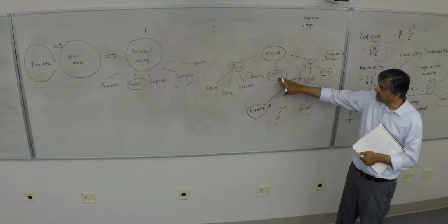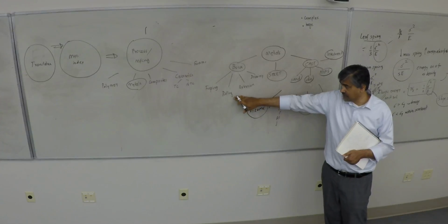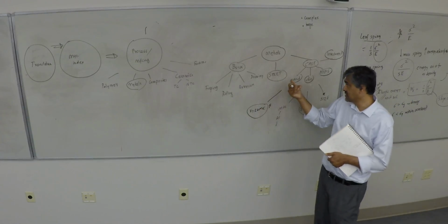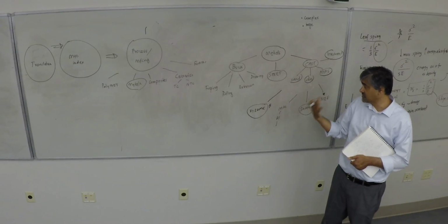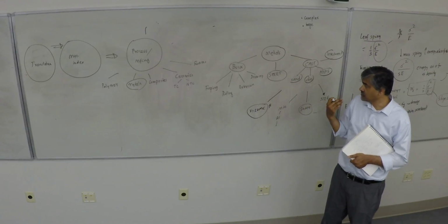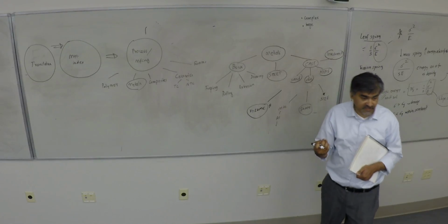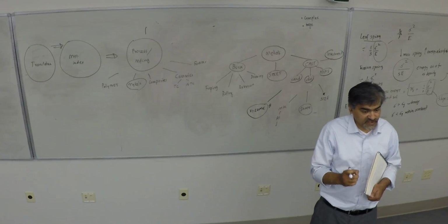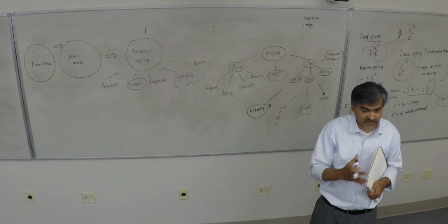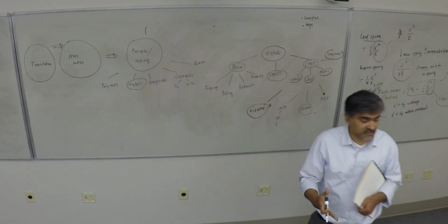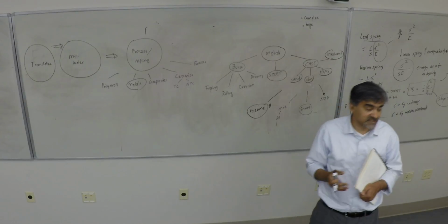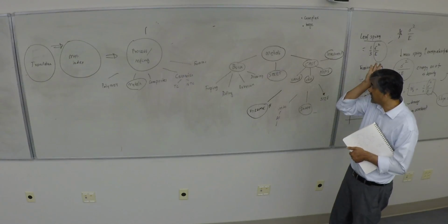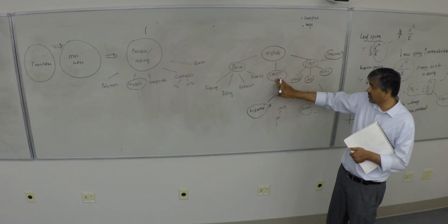Sheet parts, like we saw, have a very close alliance with rolling, because that becomes your first form for getting sheets. And once you get sheets, you usually have to work the sheets with a very constant thickness, because every time you draw the sheet on a wall or a bend, you're going to thin the sheet. So how do you manage the thinning versus stretching, right? There's a competition of strain, biaxial stretch, in that case. So those are the issues you're working with there. Again, sheet is constant volume.